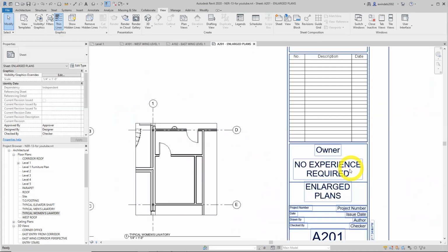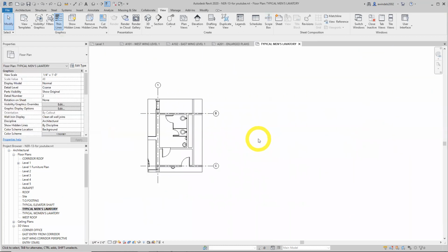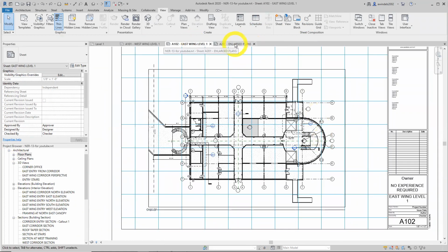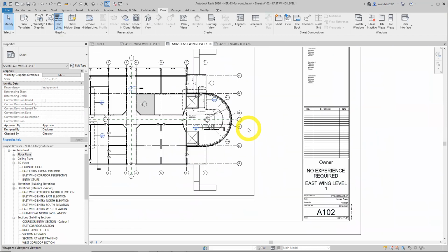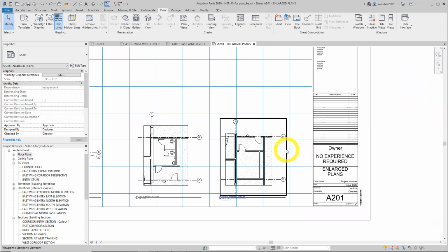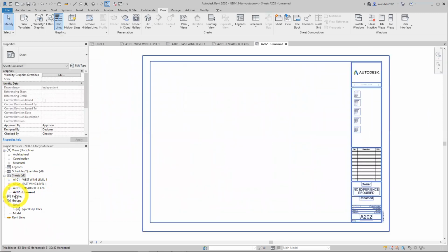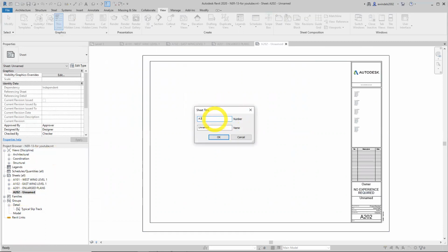And we also, when we changed our, okay, go to different sheet. That's already dynamic. Oh, my mistake. Turn this one off. I'm in different sheets here on top. It filled that out everywhere in the project name. Back to A201. We're going to make another sheet. Cascade that down. New sheets, same title block. Hit OK. Let's rename it 301.